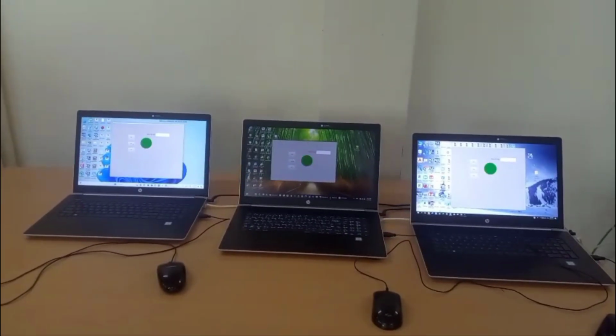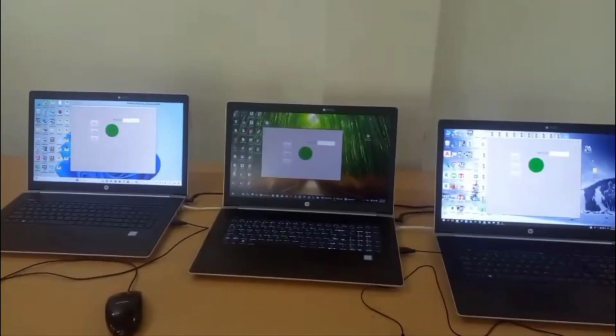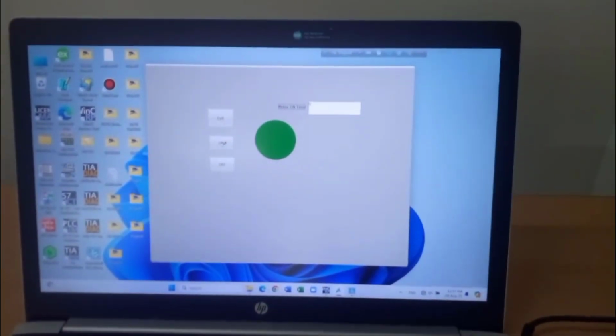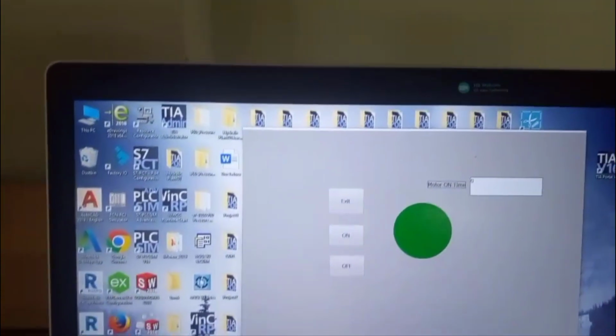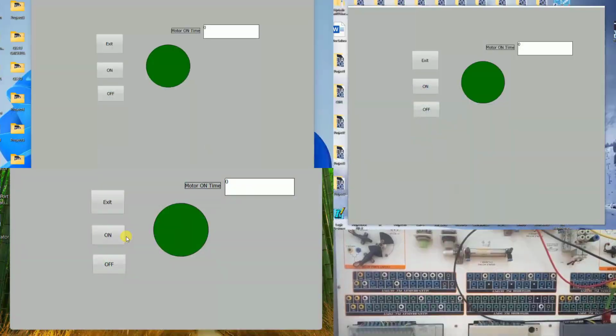In this session, I am going to show you how you can develop a WinCC SCADA system with server-client architecture. For your better understanding of SCADA system with server-client architecture, we will proceed to make a simple WinCC SCADA project with server-client architecture. When we finish this project, we will perform start and stop operation of a DC motor using an S7-1200 PLC, where the motor operation and status monitoring will be performed from multiple WinCC SCADA interfaces that have been configured in server-client architecture.